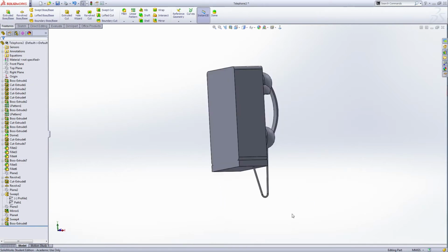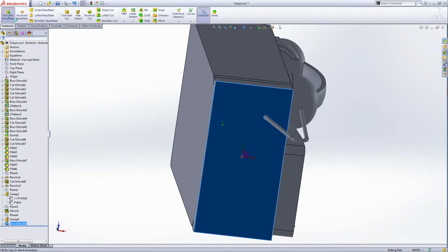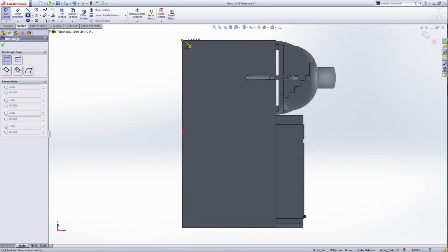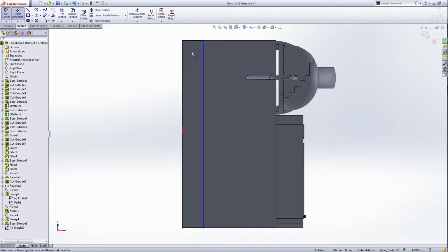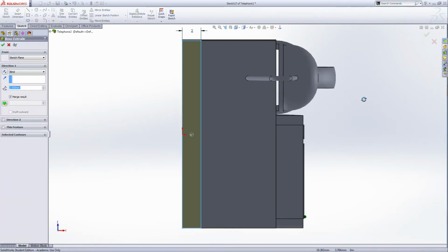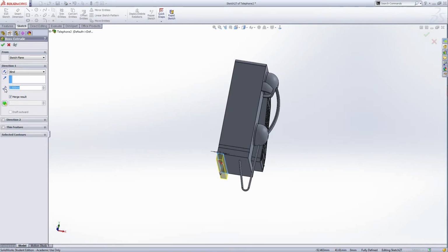Okay. Now make the leg. Select this plane and make extrude base again. Draw a corner rectangle again. So like this. Smart dimension. The distance of this is 2 millimeter. Exit the sketch. And the distance of this table is 40 millimeter. And the green check.